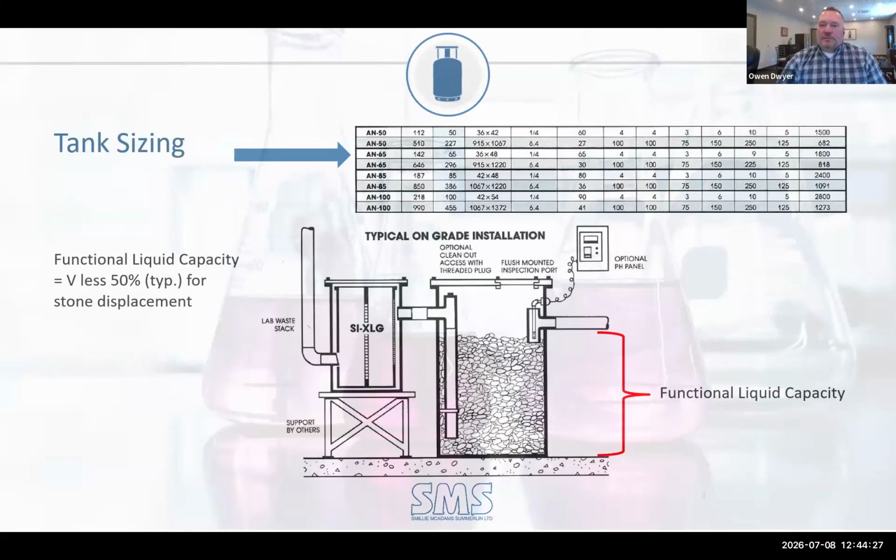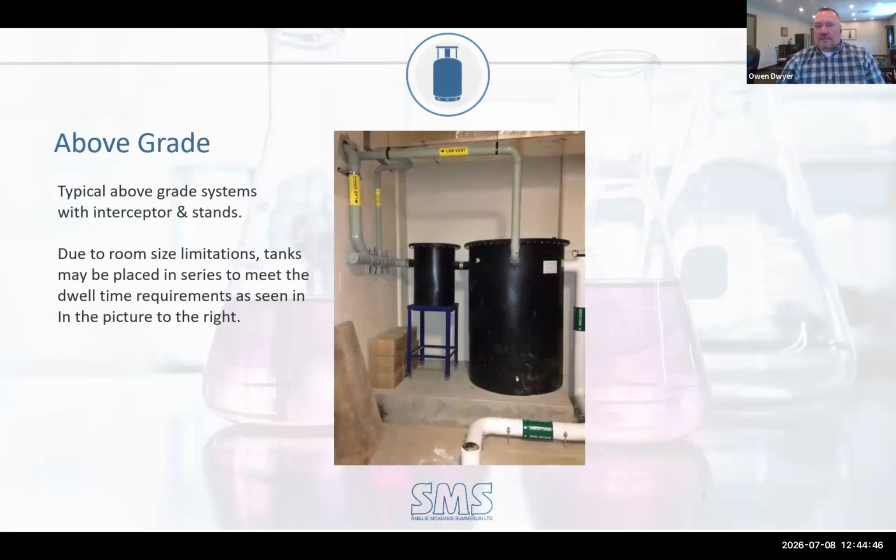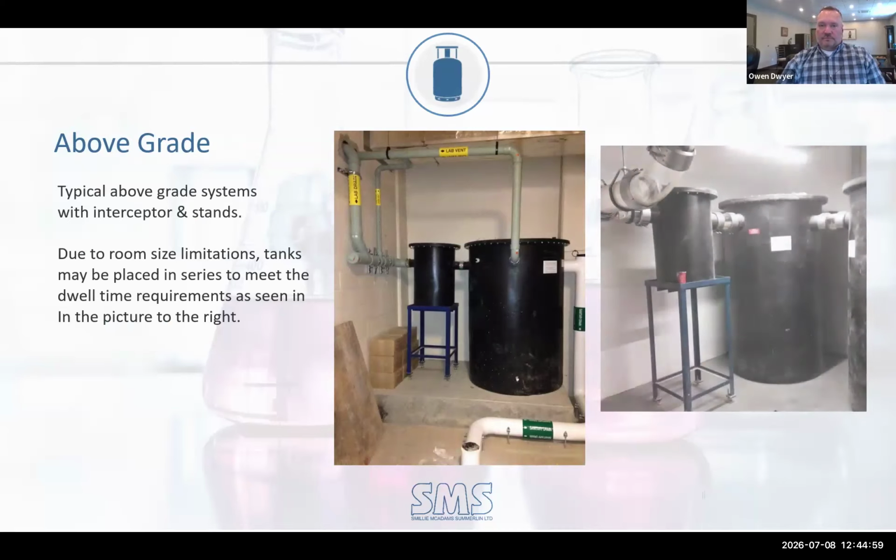So that dip tube, as Zach just mentioned, allows the effluent to percolate and have that dwell time contact with that calcium carbonate limestone on its way up to that outlet. So that's the science, that's the magic behind what we're talking about here. So the importance is in the detail. Again, here's an example where you can see on the left-hand side there are some boxes of stone. Specify some additional refill of limestone so they don't have to guess. They're not going to go to the garden center to find some extra limestone.